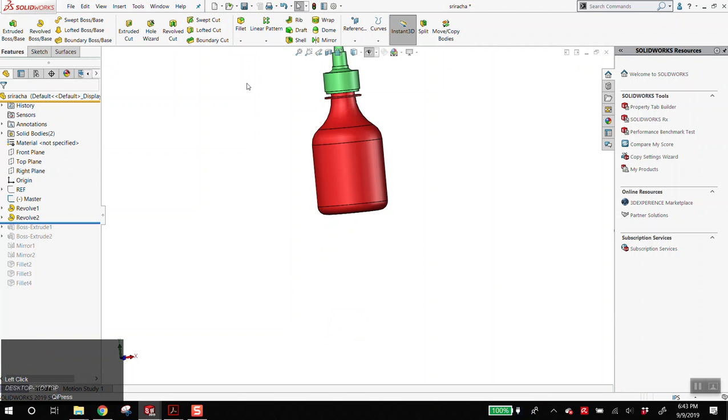So my advice to all of you is to, between now and Wednesday, really nail your master sketch. And now that you're aware you're going to have to change this, play with it. Just try saving a copy, change the dimensions, and make sure it doesn't blow up. I would argue the hard work is done. You have the master sketch set up. Now you just need to dimension it in such a way that you're aware that the base is going to have to grow both in height and length. Once you have that figured out, it's not hard to just change and check. It shouldn't take more than 10 minutes.